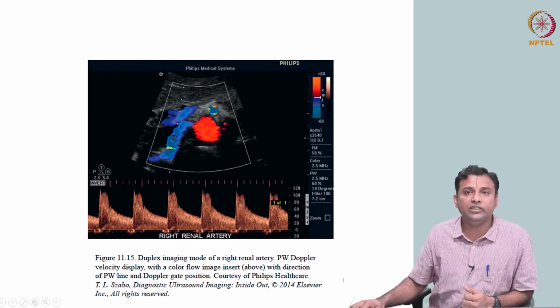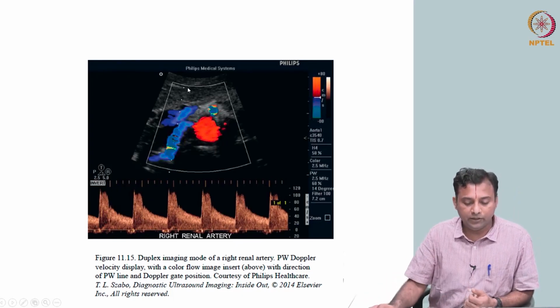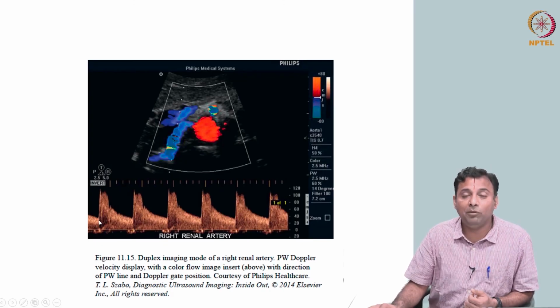that is called a range gate. Range is distance, so gate means range gate. Within this range gate, remember we calculated fD, the Doppler shifted frequency. Your Doppler frequency fD is plotted here, within this small window in this range gate, because there is flow.